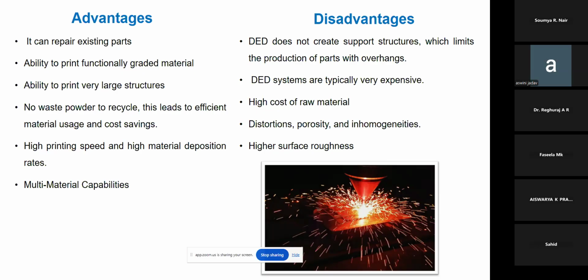DED systems are typically very expensive. High cost of raw material. Distortion, porosity, and inhomogeneity in the printed component. And also it has a poor surface finish. So these are all the drawbacks or the limitations or setbacks in the laser DED.